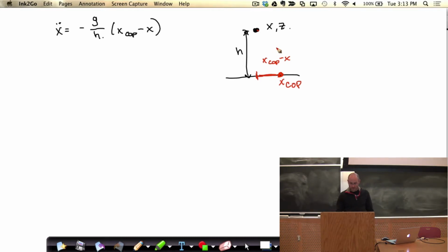This is a fundamental property of pushing on the ground, right? It's true for a compass gait. It's true for a rimless wheel. Those guys are going to have trouble keeping their center of mass at a constant height. But the dynamics, before I made the simplification of z double dot equals 0, are exactly true of any walking robot, or any robot pushing on the world. As long as we're talking about contacts all in a plane, these are exactly the right equations.